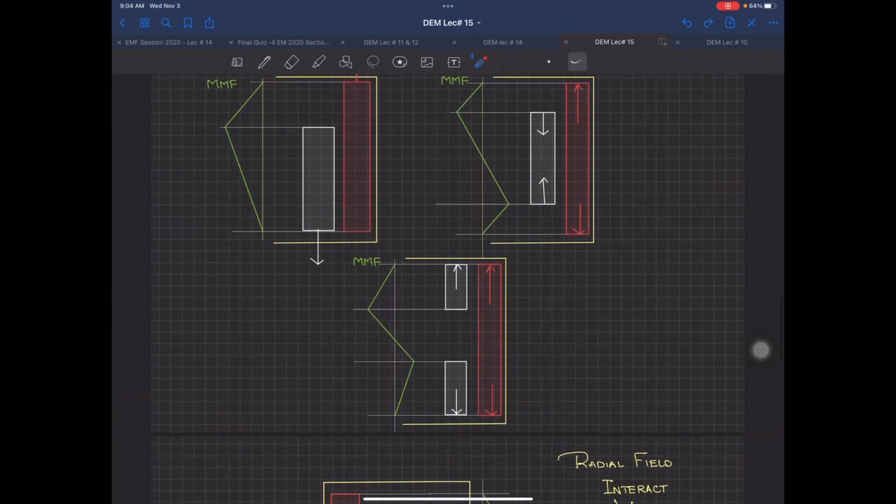But whenever there is going to be unsymmetrical windings, there is going to be a problem over there in the event. That's why as a designer, it's your utmost responsibility to have the low voltage and the high voltage winding as equal as possible. And in distribution transformer, this problem is even more severe. Why? Because in distribution transformer, you are coming on from 11 kV to 400 volts.